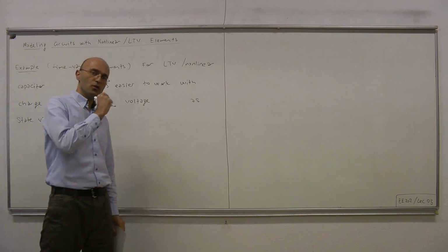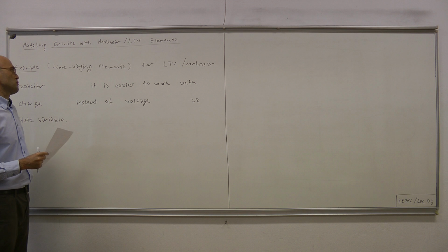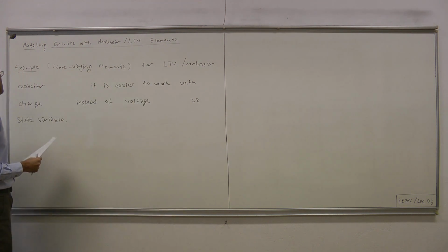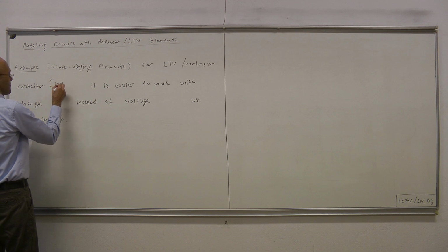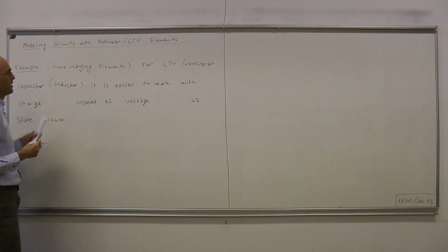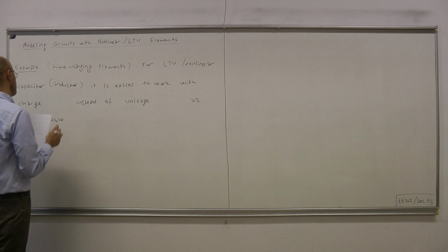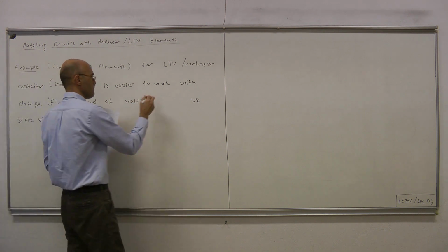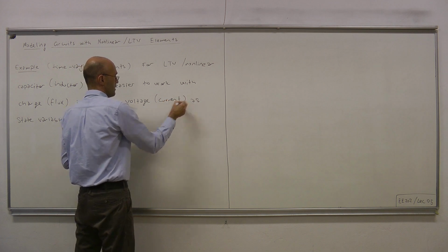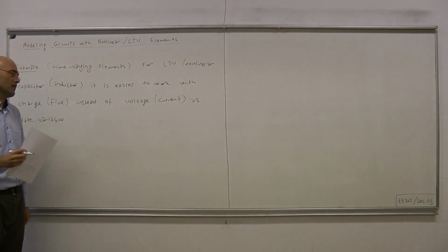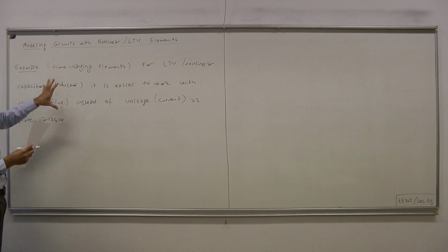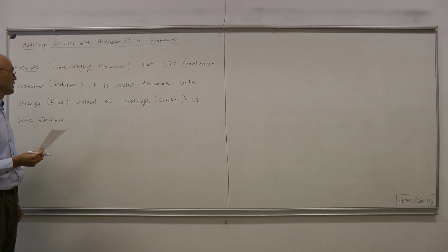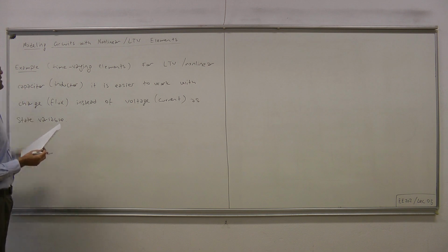And the dual statement is also valid, meaning that for a linear time varying or nonlinear inductor, it is easier to work with flux instead of the inductor current. Now we're gonna apply this way of looking at things in our linear time varying circuit